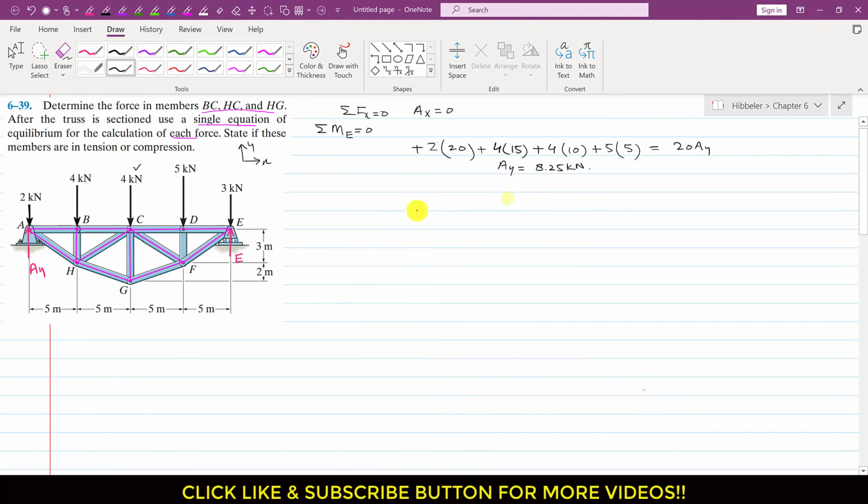So now we know the reaction at point A. This is 8.25 kilonewton. Now I have to pass an imaginary cutting section, and that cutting section needs to pass through these members which we are required to find the force for, right?